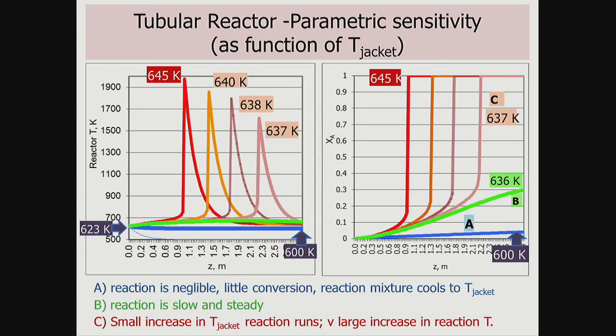Remember what I said about the Langmuir-Hinshelwood and all that? You're looking for the one that's the rate determining step, the slowest step. That scales everything. But you're also looking for something that might be a bit hidden from view. Is there a secondary reaction that's exothermic? Is there a secondary reaction that's really endothermic that's going to chill everything off and the damn thing stops?